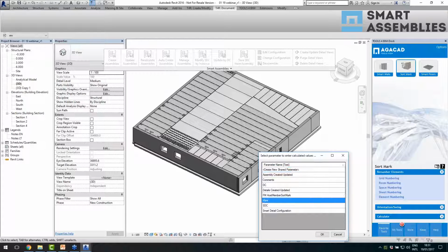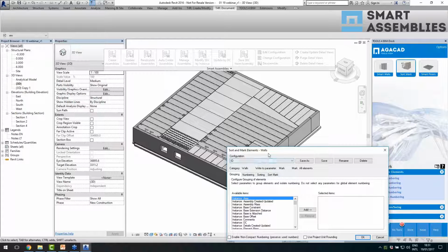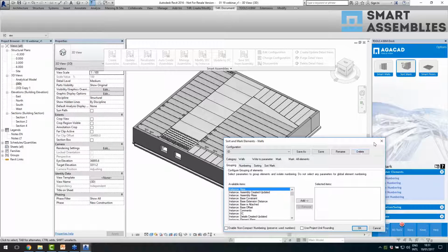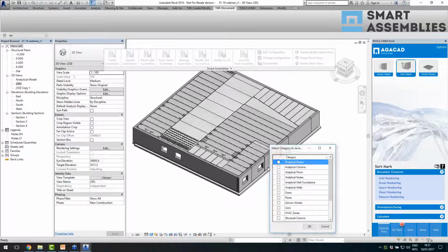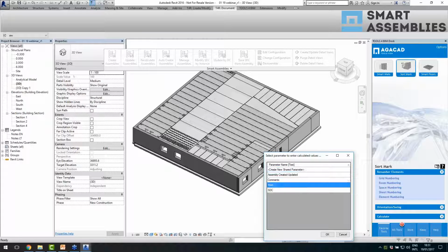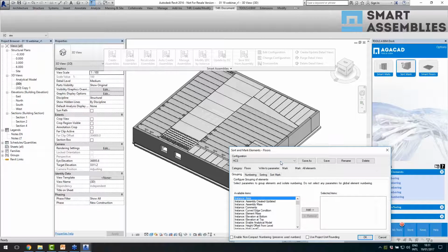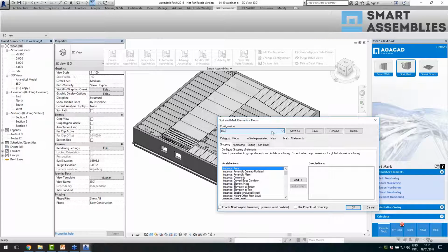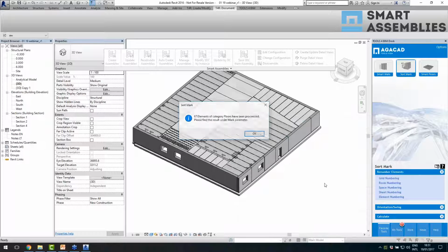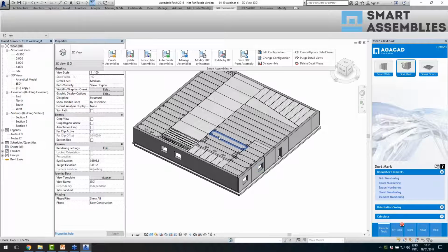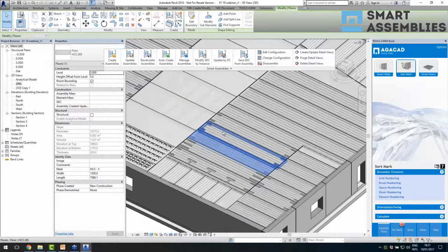I would like to renumber also the, sorry, did I select the walls again? I want to select floors. So that was my mistake. Let me select this again and do a mark and just renumber, because for the assembly I need to have mark values. Okay, I think that's all right, because when I create assembly, it takes mark value and it just names the type of assembly according to this mark value.